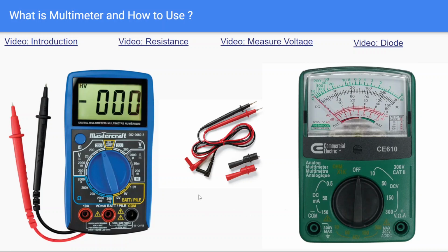Okay, so multimeter is called multimeter, but meter means measuring. Multi means numerous, so it's a meter which measures numerous parameters. Most commonly used multimeters in the lab measure voltage, as you can see here. It can be AC or DC. It measures resistance, as you can see here for the ohm, and it measures current, as you can see in this particular section. There are also battery related features, but these are the three most common features you will find in the multimeter: voltage, AC or DC, resistance, and amps.